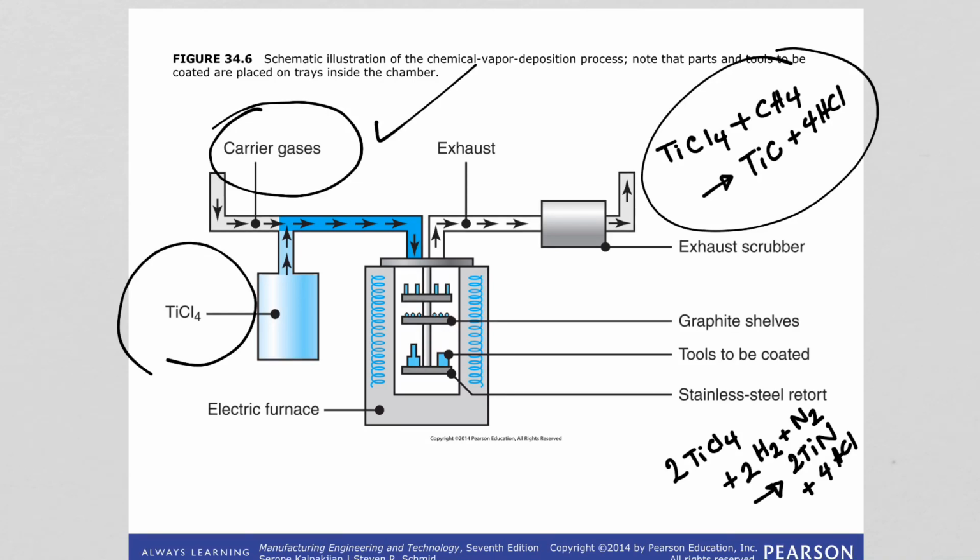So in general, CVD coatings are thicker than PVD, and it is a long process. It might take hours of heating, coating, and waiting for it to cool to room temperature. But a lot of parameters you can control: the thickness of the coating with the temperature, time, or flow rates of the gases that are being used.